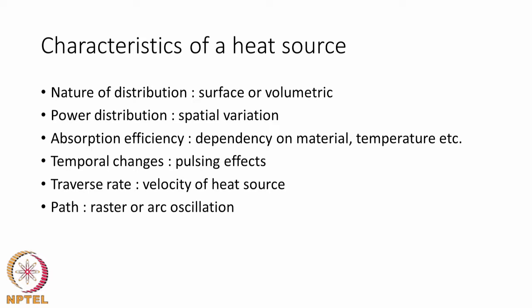Does it move linearly or does it move in a zigzag manner is also something that is going to play a role. So, very often the path that is taken by a weld heat source is linear and it can be programmed by a single drive, but there are situations where you may have a rastering action for the heat source. By rastering, what we mean is moving back and forth to cover a wide area. This is often practiced in situations where a very wide pool is required, however, the heat source is focused, that cannot be extended to that much of a width.